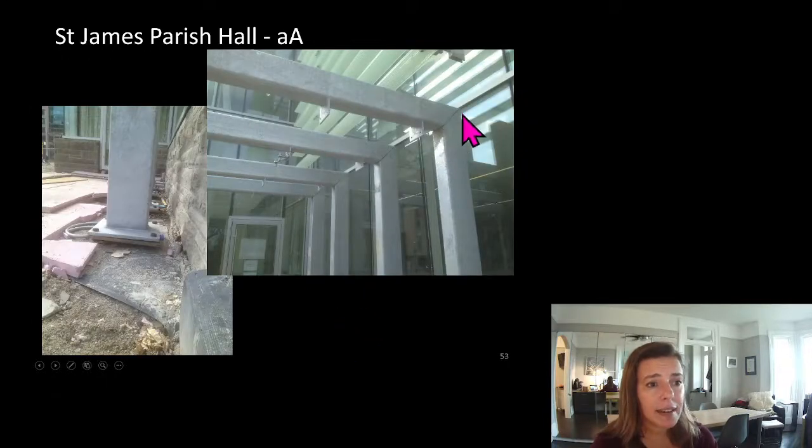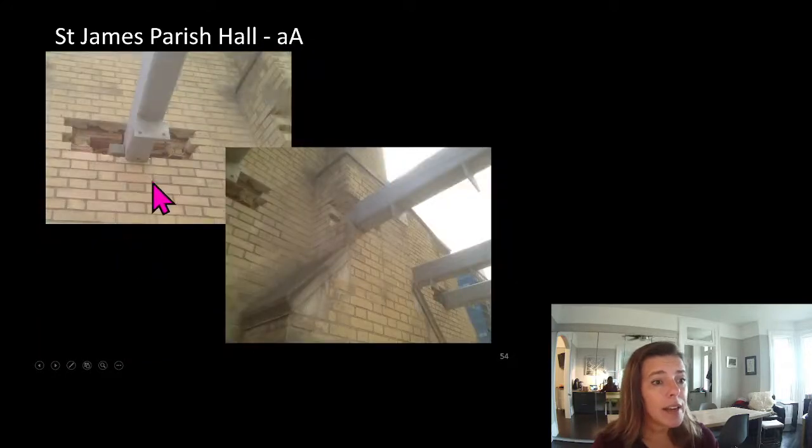Here is the detailing. Look at that beautiful crisp line that we had here, where they didn't want to do welding on the site, which meant that if water got in here, we needed water to be able to drain out. Here is our connection where we had stubs attached to the structure below that came out, and we connected these plates to the stubs. And here is our roller detail on the existing St. James